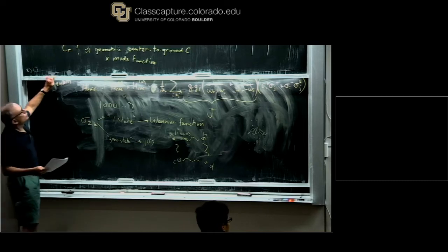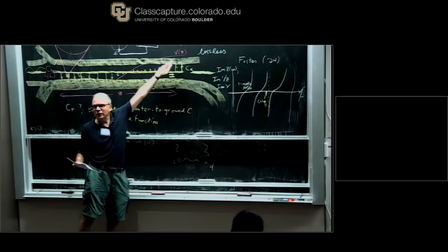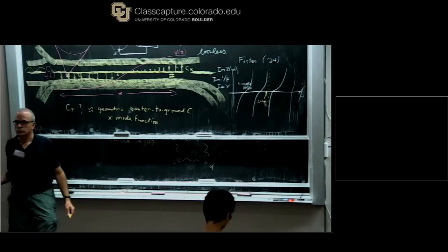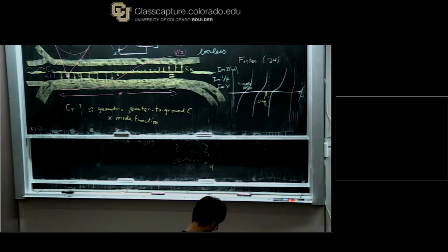Now the simple rule of thumb is I've got a second transmon, it's at a different place in the mode profile, and that's its G. Its location in the resonator determines the coupling. Physical location determines the coupling, yes. Not C r, because they have the same C r. Well, okay, now it depends on whether there's the C coupling, but then you get all the way to G eventually.